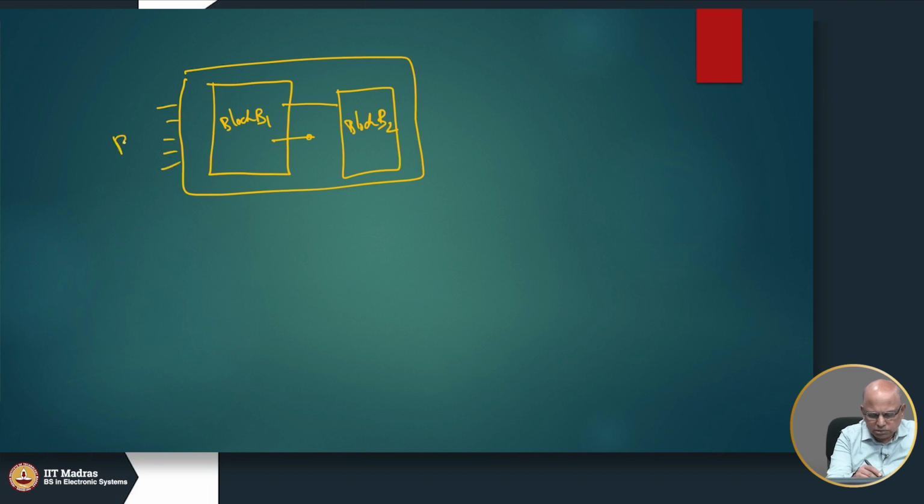These are the primary inputs and these are the primary outputs. So, if there are such wires, okay, you cannot find many faults which can be propagated to this. For example, stuck-at faults at these points cannot be found. Okay. So, stuck-at faults here cannot be detected.